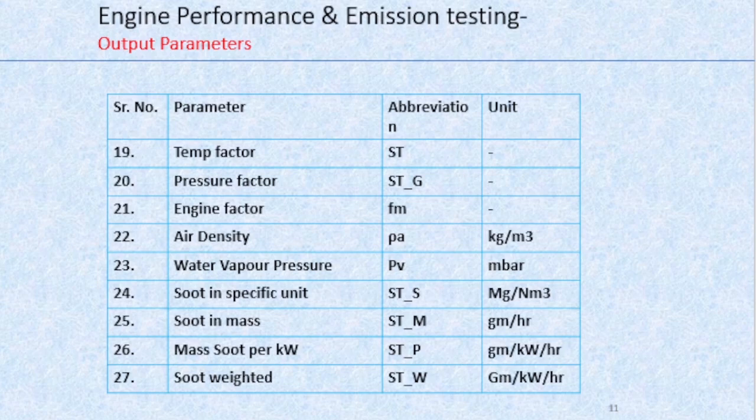Now here, the parameters listed are temperature and pressure factors, which have been defined as per standards towards calculation of the overall engine power correction factor. As per application, the correction factor is defined as the multiplication of the temperature and pressure factors, having A and B indices on the respective ratios.